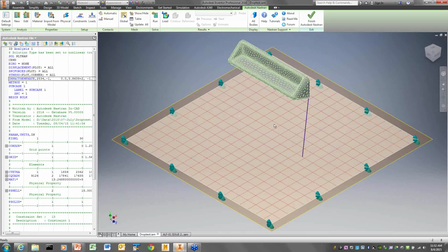And so that's the first thing I'd look at: check units. Do the units of my distance look right? Do the units of my density and my mass look right? Are my velocity and acceleration units consistent? I had a great problem with someone who was doing a shock analysis one time, and the paperwork located the explosive in feet away and inches below. They had blindly copied the numbers and ended up locating the explosive inside the model, which was very spectacular watching a simulation of a model explode, but that was not what they were trying to simulate.